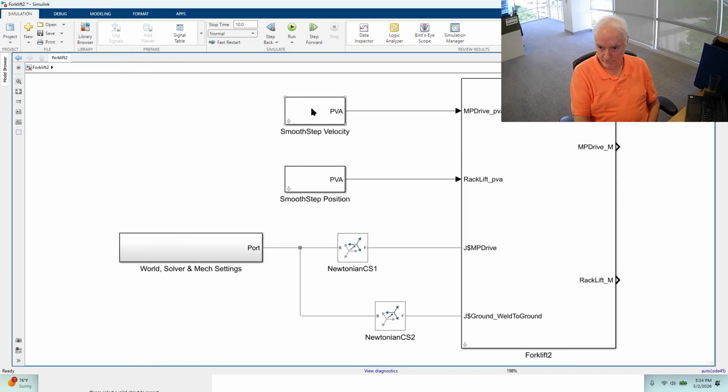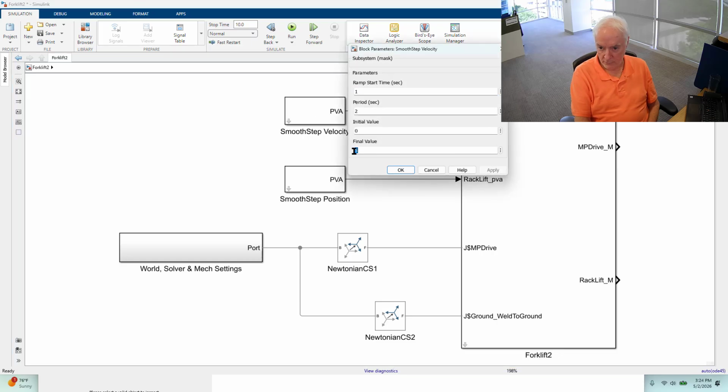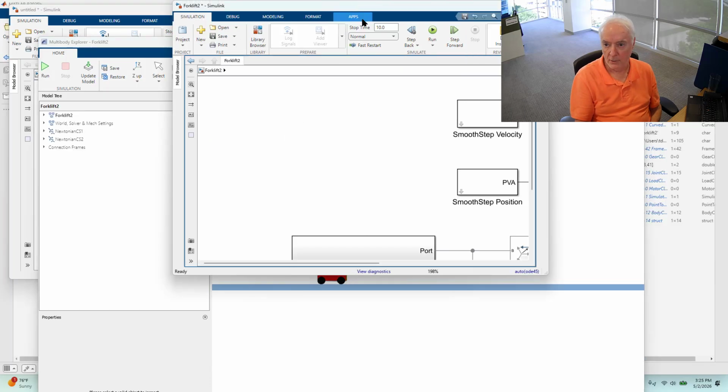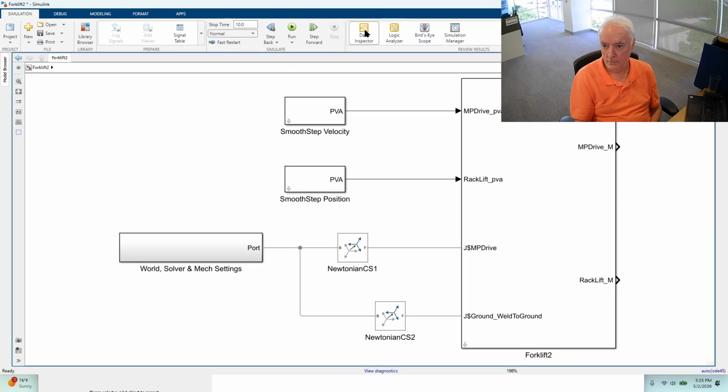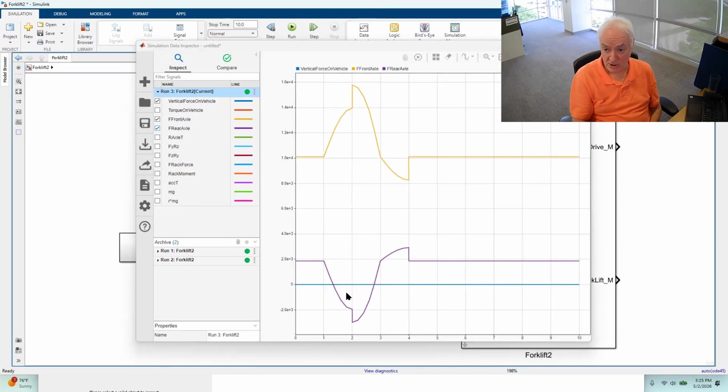And so just to remind you where we were with that, let's make it -5. Got it going backwards. So again, we got that violation. Well, I think it might be readily apparent what the dynamics are that are leading to what we're observing on what's carried by the front and rear axles. Part of it's the acceleration of the vehicle, but the other part is that the forks are going up. And I do believe they superimpose, and perhaps that's maybe a bad thing to do.